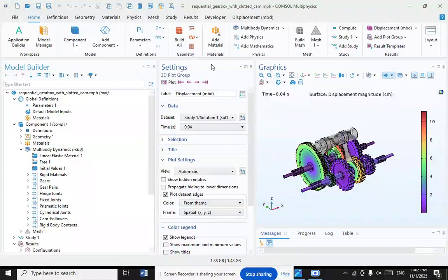Mechanical wear of the synchronizer rings and sleeves can cause the synchromesh system to become ineffective over time. These rings and sleeves have to overcome the momentum of the entire input shaft and clutch disc during each gear shift, and also the momentum and power of the engine. If the driver attempts a gear shift without fully disengaging the clutch, larger differences in speed between the input shaft and the gear require higher friction forces from the synchromesh components, potentially increasing their wear rates.